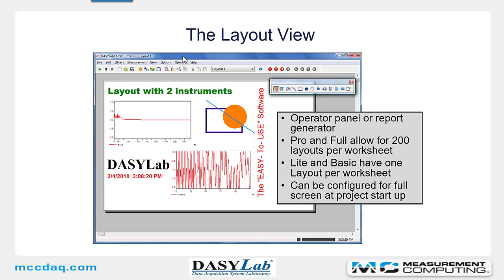As you can see in this image, the layout consists of fixed elements like text, objects like circles, lines, and rectangles, as well as dynamic information, including the date and time and any display windows that you have on your work area, so that you can display the same information without the windows dressing, just with the graphical information of the display window. When you first create the layout, it creates a new toolbar that in previous versions of DASYLab were floating. In DASYLab 2020 Service Pack 1 and on, it will be pre-docked on your screen, so you may have to look for it.